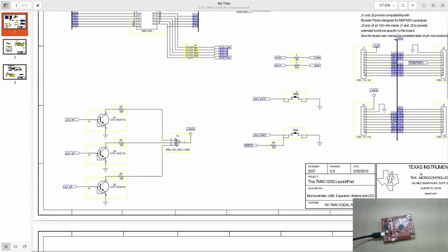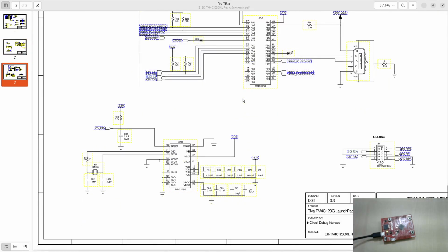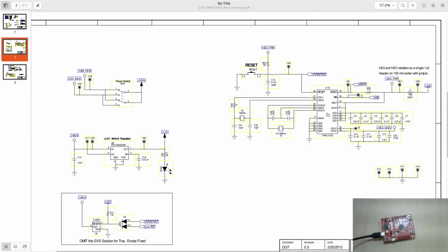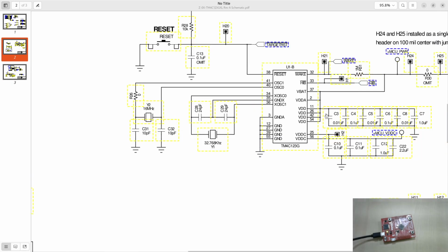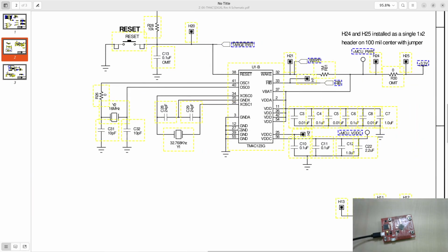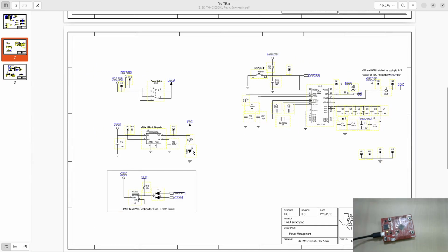And then if you search for U1 again, you will find that U1 may be appearing in other places as well. So you can see this is U1B. Parts of the IC, for example the ground pins, the power pin, the crystal oscillator, reset pin, wake up pin, all of these things, they just split into different blocks. That's all. U1A and U1B both refer to this particular chip, which is the one we are working with, and we are going to program and dump our code into this.